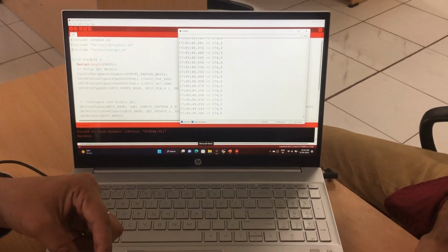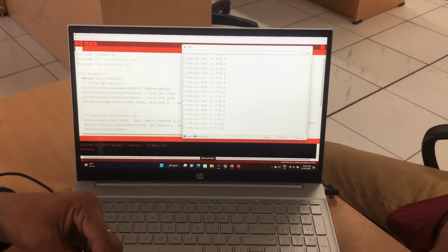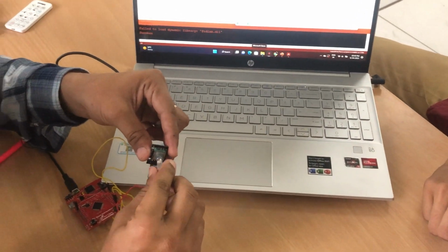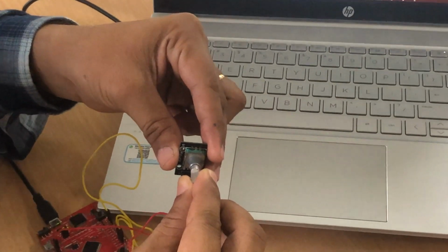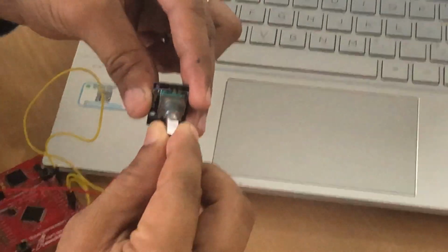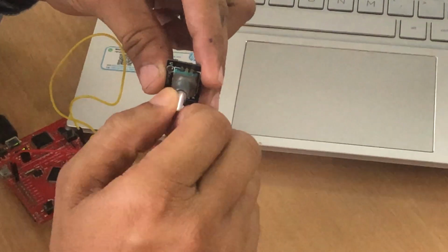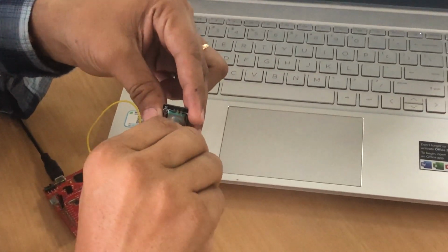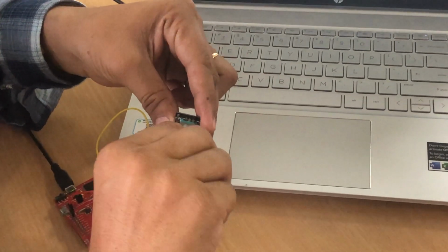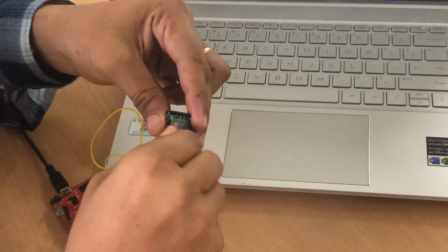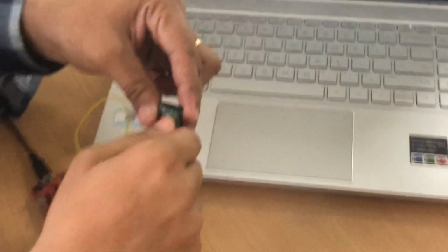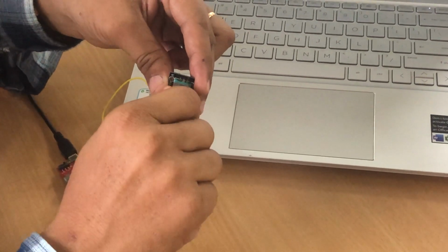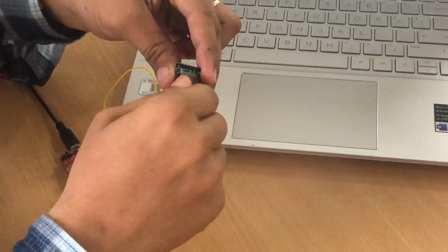This is one way to understand how the wheel speed sensor works. What I have in my hand is a rotary encoder knob. In all electronic equipment nowadays, we do not have potentiometer-based knobs. In modern washing machines and modern music players, you do not feel the potentiometer experience; you feel something like tick, tick, tick. These are all rotary encoders, where there is no wear and tear, and they are very reliable, and there is no need for an ADC. If it is a potentiometer, we need an ADC. So it avoids the ADC. Why?